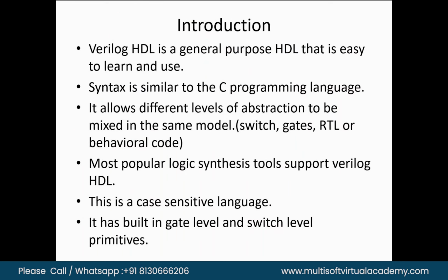As I already told, Verilog is a general purpose HDL. It is very easy to learn as well as use, and the syntax is similar to C programming. It has different levels of abstraction mixed in some of the models. Different levels of abstraction means you can write switch level modeling, gate level modeling, transistor level, or behavioral code.